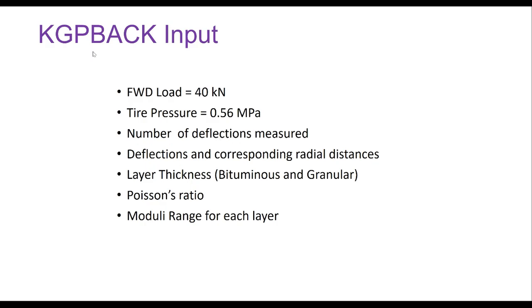The inputs to this software are the load, that is 40 kilonewton, tire pressure 0.56 MPa, how many deflections are measured and what their distances are, and layer thickness.